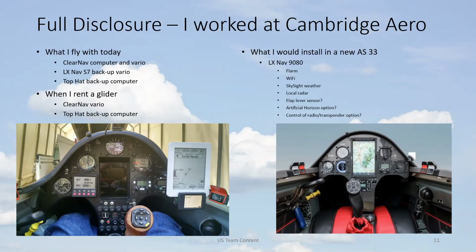One comment about something that was said a little while ago. I would be very cautious about connecting two batteries to each other without electrical protection. And I would be extremely cautious if the two batteries were lithiums. If they're at different states of charge, that is one of the things that has the potential to cause a fire. It's not something that I would play around with. Yeah, totally agree. Yeah, but that's why you'd have fuses, right?